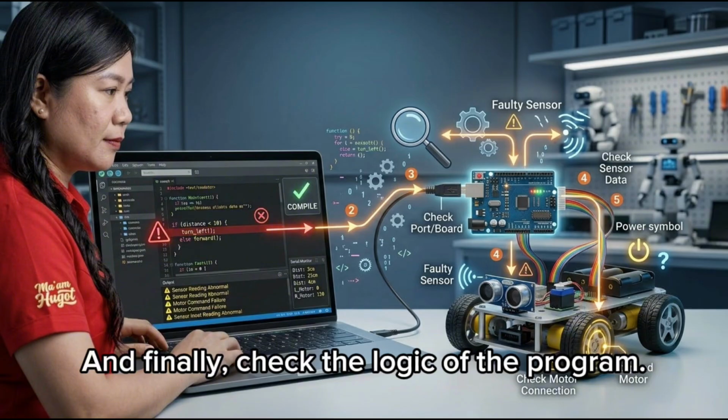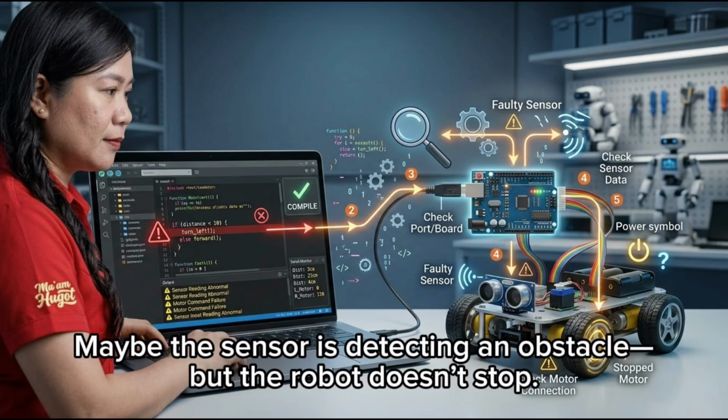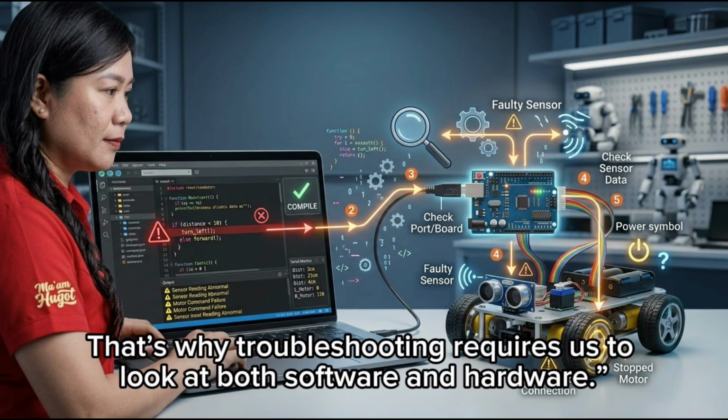And finally, check the logic of the program. Maybe the robot is moving, but in the wrong direction. Maybe the sensor is detecting an obstacle, but the robot doesn't stop. In these situations, the program may run without producing a compilation error, but the robot's behavior is still incorrect. That's why troubleshooting requires us to look at both software and hardware.